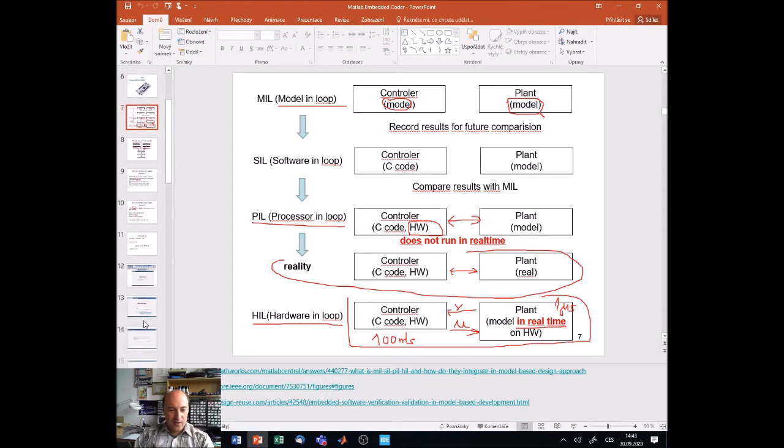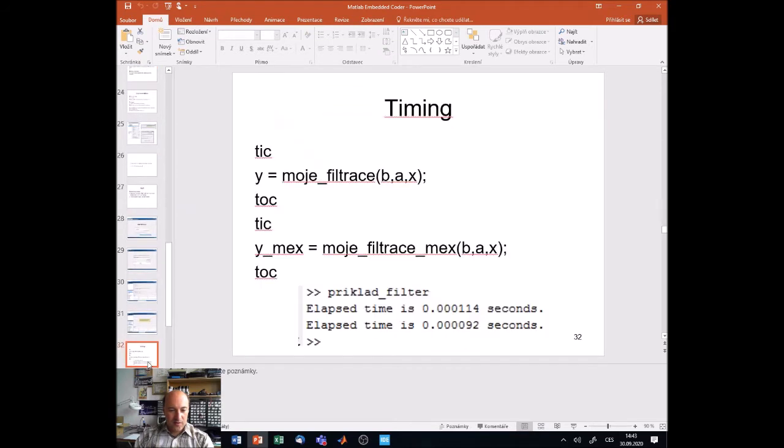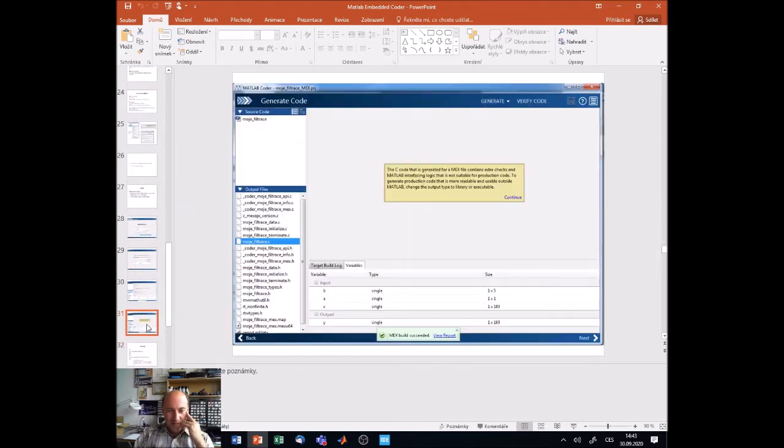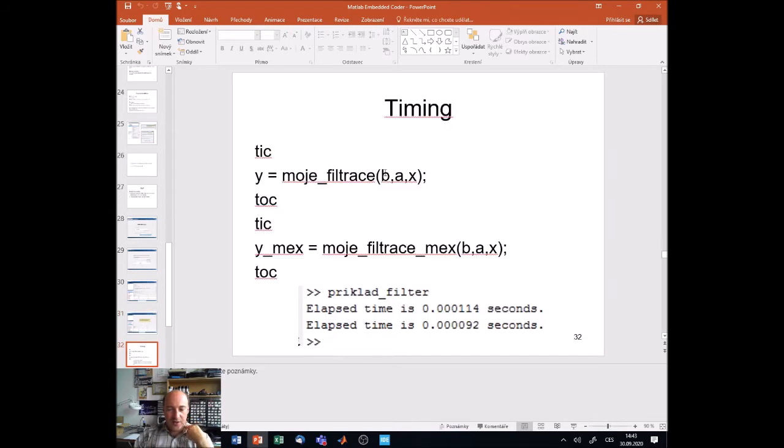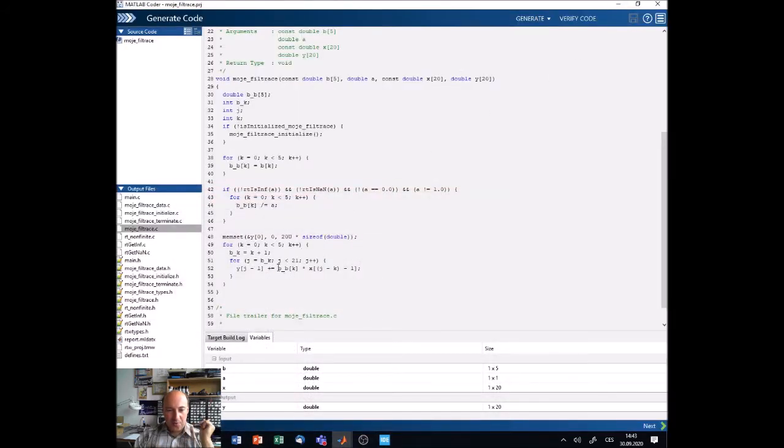So if I look now at my results in MATLAB, those coefficients that you see here, the b, are all equal, and a is equal to 1. If I see in MATLAB that it's multiplying with this coefficient, then I could easily replace this with some constant number. If you know in advance what your filter coefficients are, and if they are all the same, you can do this. But this is more of a universal way of writing it.